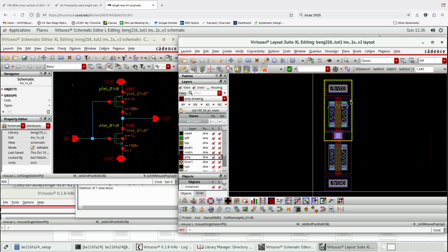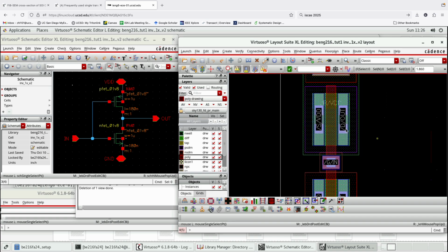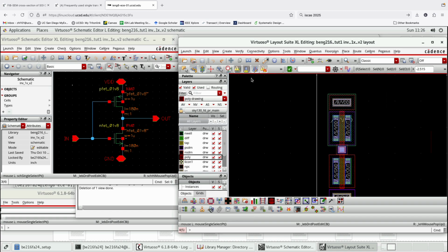But running DRC takes extra time, takes extra effort. So that's why here we prefer to have DRD, which is real-time rule checking, to be turned on. So we have notify on and post edit on. And if I make some weird mistakes later on, you'll see that something will remind me that I made a mistake. You can also consider turning on this DRD enforce off or on.